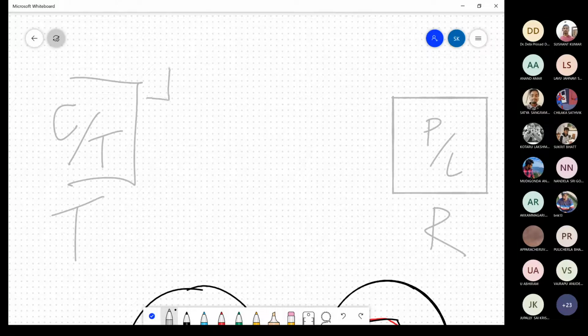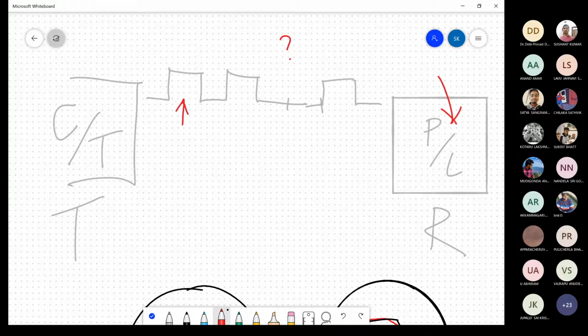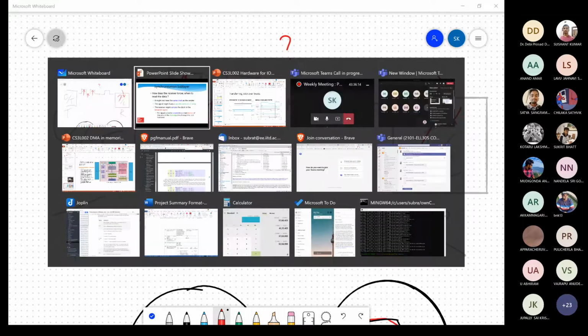If you have a signal like this, let's say this is the transition period to the clock. Suppose I have a signal like this, then how does this fellow know how to sample the signal? Right? We know that we are supposed to sample the signal here, right? We are supposed to sample it here. We are supposed to sample it here. But how does this fellow know? So that's the question which is being asked. So one of the ways in which we do it is we try to recover the clock. I'll come to that maybe for a slide if I find a slide on that.